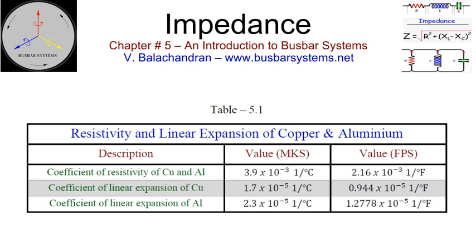When a conductor carries alternating current, its resistance value RAC is always more than RDC at the same temperature. As will be seen in the following discussions, the increase in the resistance is due to skin effect, when in isolation, and a combination of skin effect and proximity effect, when with an adjacent conductor, of the same phase or different phase, carrying current.